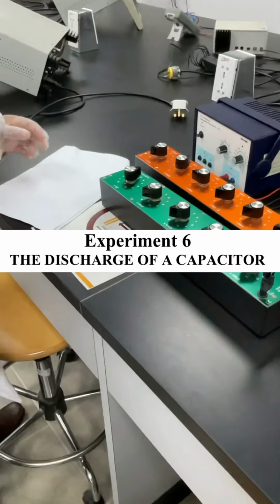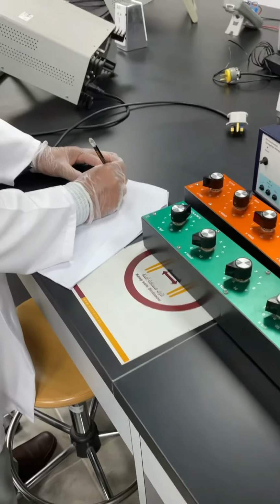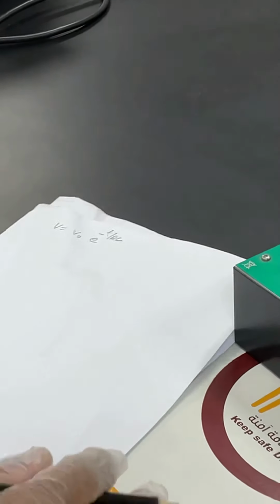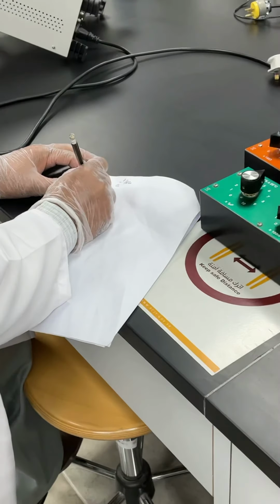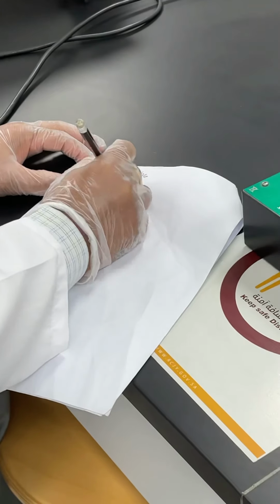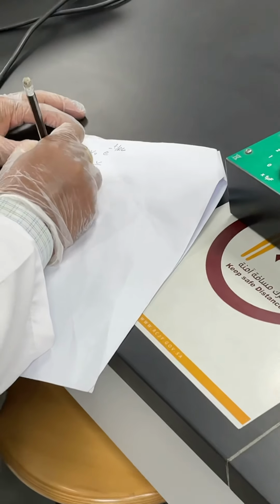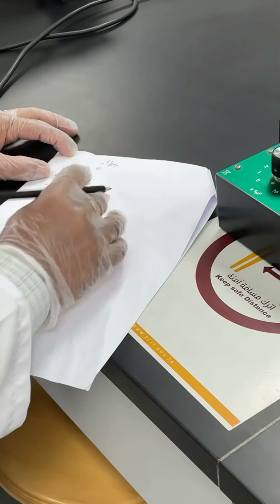The input impedance of your voltmeter. For this, the formula will be given: exponential of minus T by RC. This formula will be given. I want to find R. How to get it? Let us play with this equation. Exponential of minus T by RC is equal to V by V0. If I want to remove the exponential, what should I do? Minus T over RC is equal to ln (V by V0).